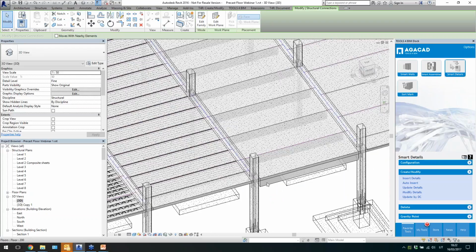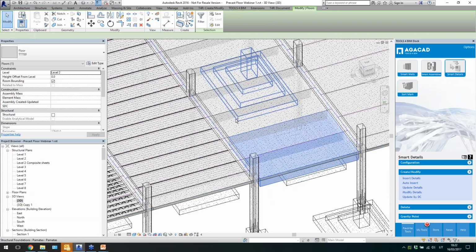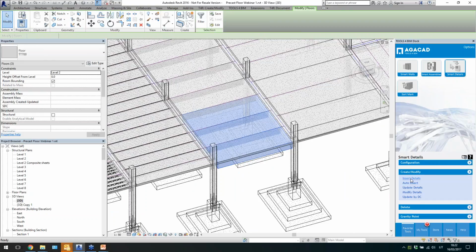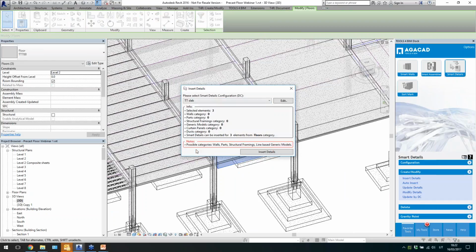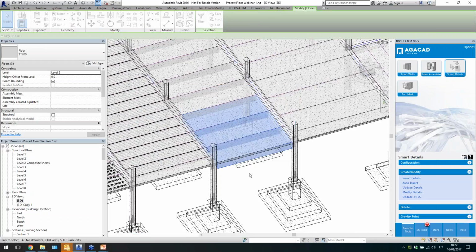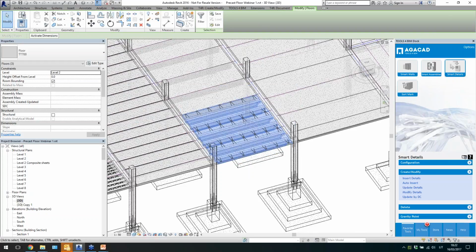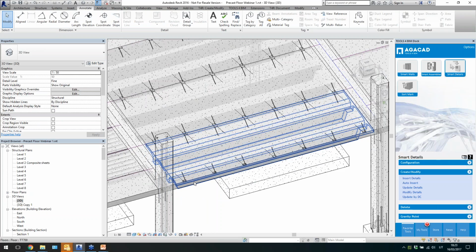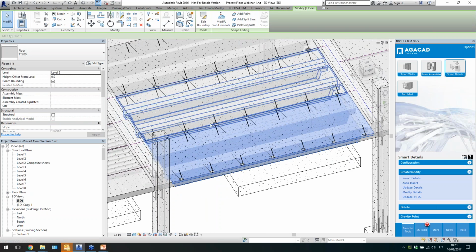So let's say this kind of floor, then okay, I will just select a couple of these floors and I'll just do it like this. I will actually create double T slabs with this command. Like previously I created this by using structural framing element, but now I think it's pretty cool to use floors for this, because you can easily divide them.